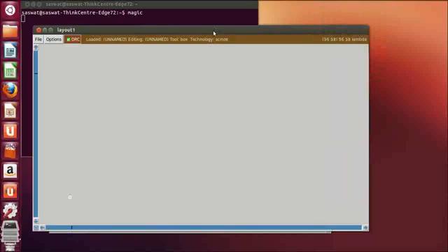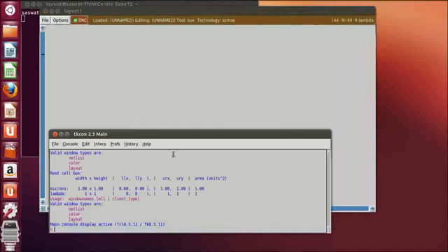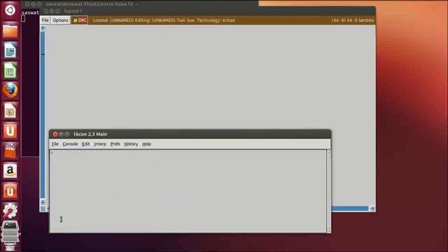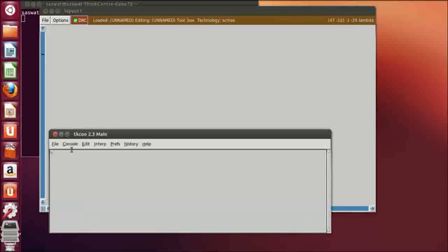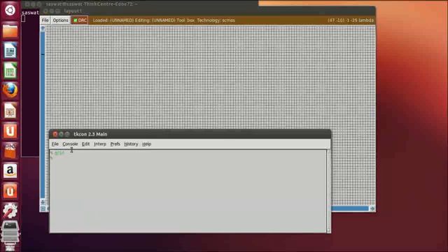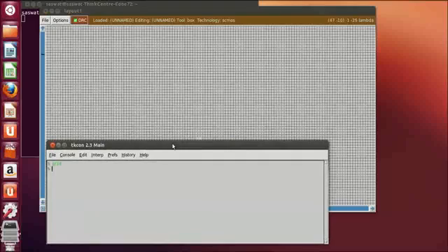So this is our layout window, and we have to type the commands in the tkcon window. First, clear all other commands present in the tkcon window. Type clear. Okay, now we can see there are no boxes present here, so we have to first grid it. So type grid.